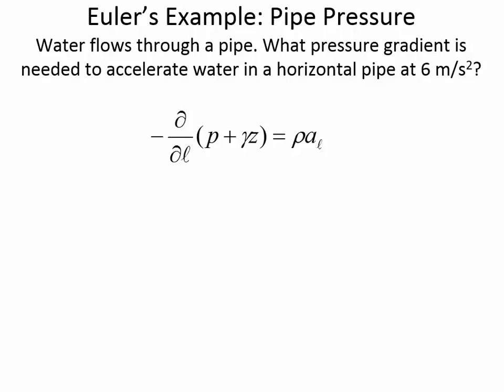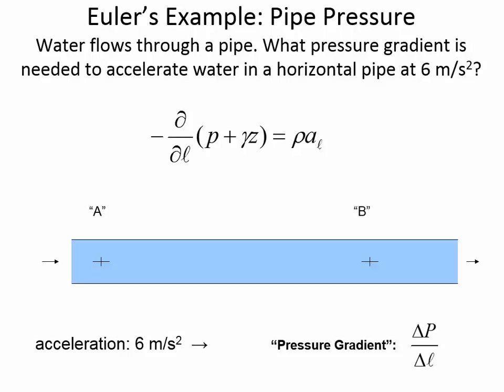Water moves through pipes because of pressure gradients. That's what drives flow: somewhere down the line the pressure is low, and so the water is flowing through the pipe to get to that point of lower energy. So if we had a pipe like this, horizontally inclined, we've picked two locations just so that we can answer the question about a pressure gradient. The way to interpret that term, pressure gradient, is the change in pressure, the incremental pressure over some incremental distance.